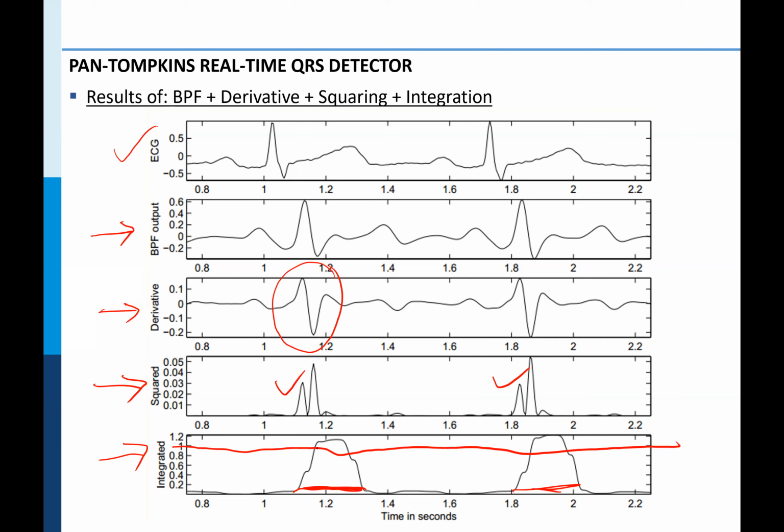For example, in this case, the moment it crosses the fixed threshold, any point above this line, it will start to count. It counts for a while, then it has no counts because nothing is crossing this line, so obviously no peaks are being detected. Then again it starts to count. Those counter values have some higher numbers, but eventually we need to say there are only two peaks.